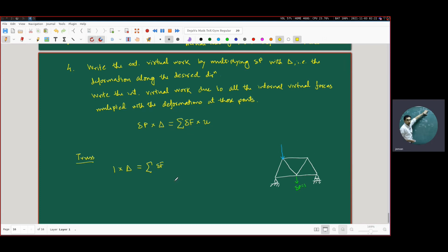Okay, so deflection associated with an axially loaded member is basically like NL by AE. So N is the actual force on that axial member, length is L, A is the cross-sectional area of the member, E is the Young's modulus. So we have to consider each of the truss members one by one.